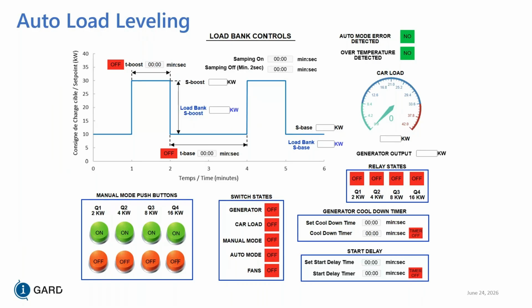So the question is, can you have a combined AC DC load bank? I guess you can, but you'd have to make sure that the contactors for the control can handle both the AC and DC currents and voltage. That seems to be a little difficult sometimes. And the cooling system has to be compatible with both. Or you're going to have two separate motors, two separate sets of loads. It becomes more difficult.